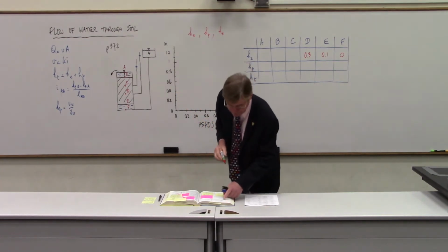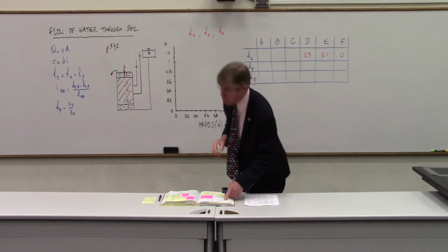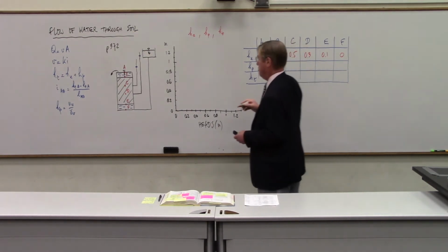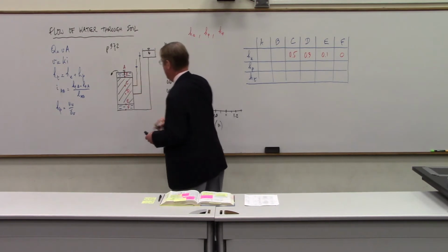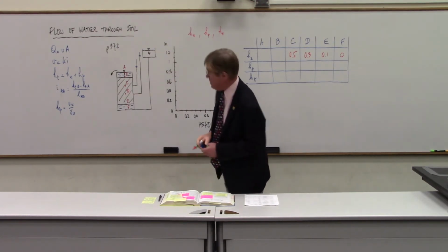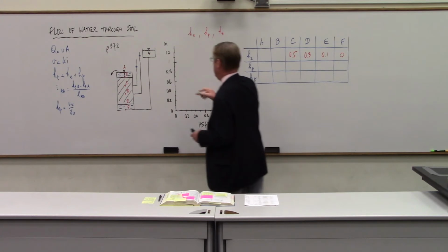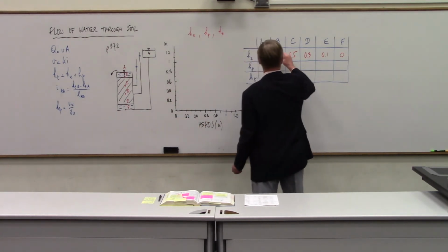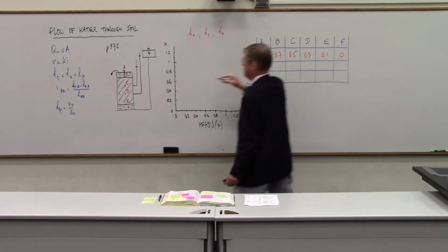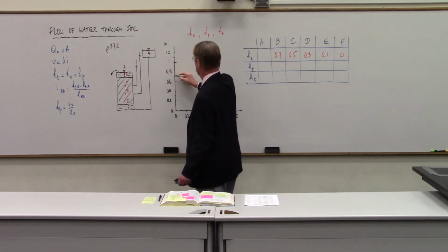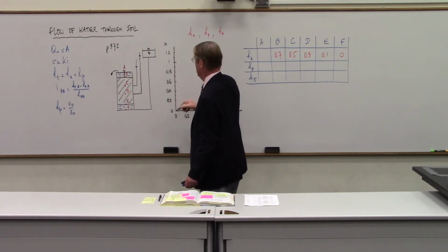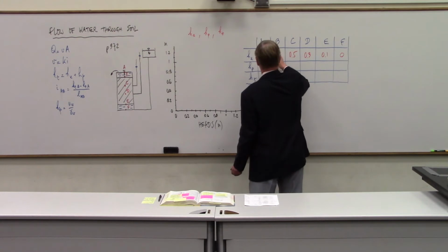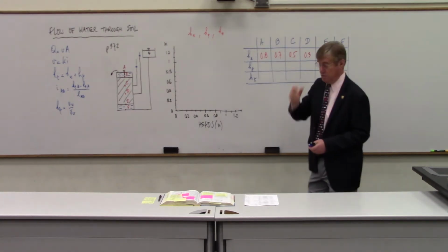At C, it is 0.5. When I look at the diagram of the book, the C and D are a little bit higher. And then at B, we are at 0.7. Okay, that's correct. Again, all I'm doing is looking across and reading this number here on the vertical scale. And A is at 0.8. All right, done. We've got elevation head everywhere.